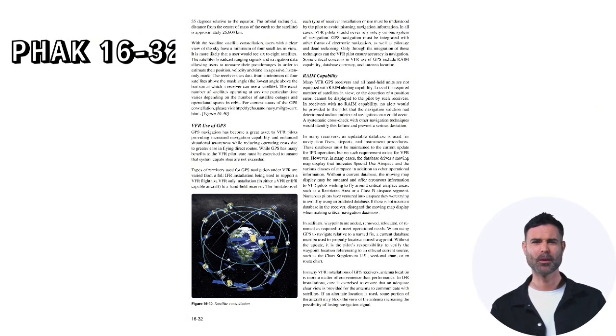GPS navigation has become a great asset to VFR pilots, providing increased navigation capability and enhanced situational awareness while reducing operating costs due to greater ease in flying direct routes. While GPS has many benefits to the VFR pilot, care must be exercised to ensure that system capabilities are not exceeded. Types of receivers used for GPS navigation under VFR are varied, from a full IFR installation being used to support a VFR flight, to a VFR-only installation in either a VFR or IFR-capable aircraft, to a handheld receiver.